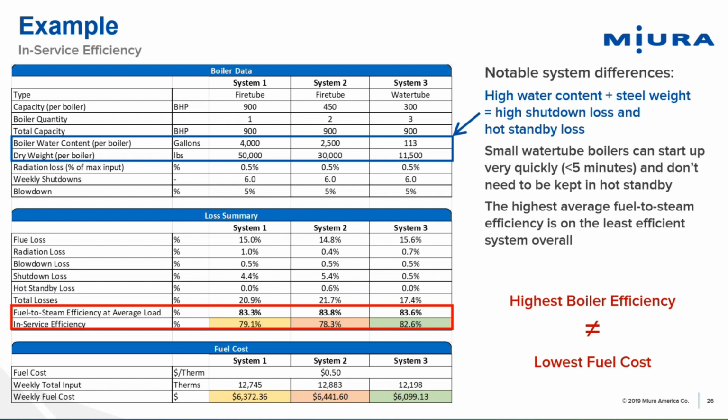So to answer the question that just came up in the chat, the highest efficiency point is a boiler that never comes on at all, right? That boiler has not lost any fuel. But ignoring that, the next highest can be anywhere, right? I think it tends to be in the low to middle fire range is where it actually kind of peaks. But every boiler operates a little bit differently. So you have to look at each boiler individually to see where its highest efficiency point is. Some manufacturers can help you determine that and figure out how to size your boiler so that it tries to run at the highest efficiency point all the time. But it can depend a lot on a number of factors in the boiler.